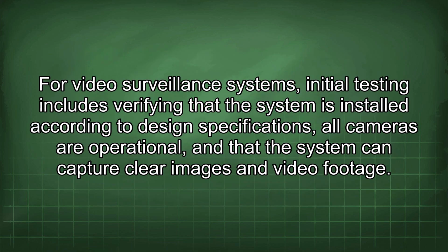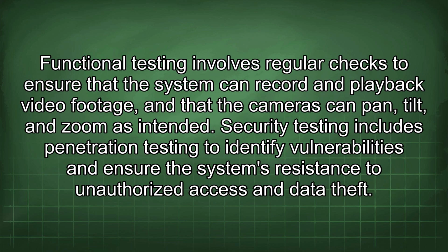For video surveillance systems, initial testing includes verifying that the system is installed according to design specifications, all cameras are operational, and that the system can capture clear images and video footage. Functional testing involves regular checks to ensure that the system can record and playback video footage and that the cameras can pan, tilt, and zoom as intended. Security testing includes penetration testing to identify vulnerabilities and ensure the system's resistance to unauthorized access and data theft.